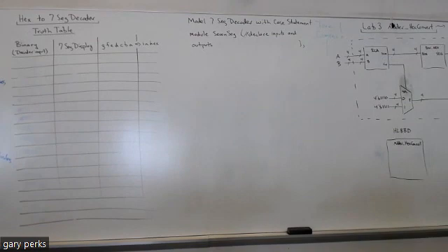Well, let me ask. So everything to the right of this NOT gate, you're good with? Okay, so, we could take that NOT gate out, just have a straight connection from this AN input right to the common anode. But if we did that and then made AN a 1, everything I talked about over here is still the same.